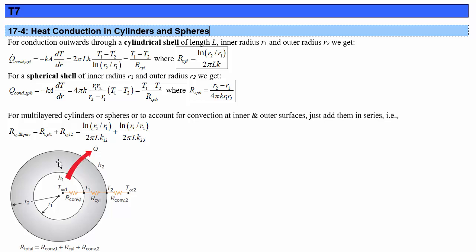So the heat flow through any surface is going to be equal to a constant as we move out through the cylindrical shell here. And from that being a constant, we can substitute in the area of each of those shells and then solve for the temperature distribution, which then gives us, once we substitute it back in, that the heat flow has to be equal to 2 pi Lk over the difference in temperatures divided by the natural log of the ratio of radii. This is outer radius of the cylindrical shell divided by inner radius.